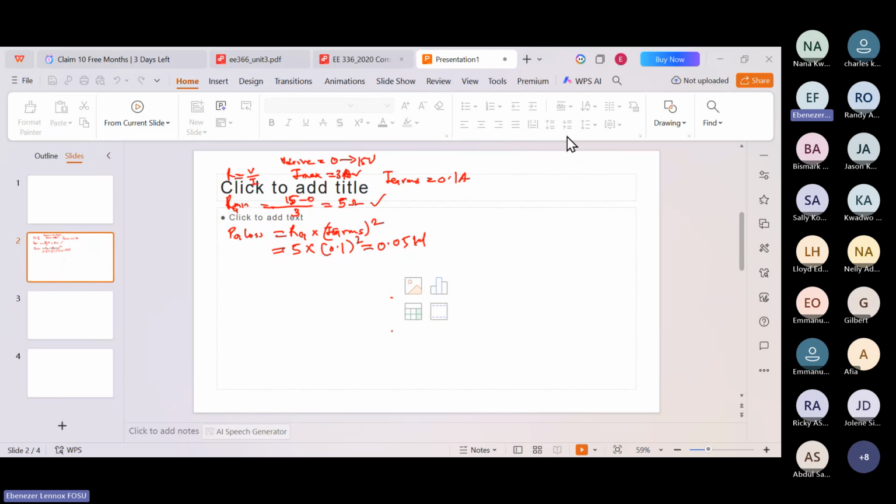So we can apply anti-log on both sides. When you do anti-log on both sides, you're going to get minus t over RC to be equal to ln of 2 over 3, right? So you have minus t to be equal to RC ln of 2 over 3. Then you can make t the subject. t is equal to minus RC ln of 2 over 3.